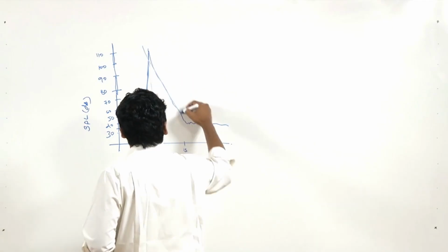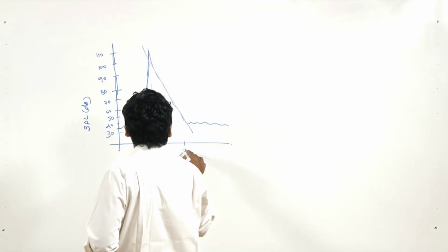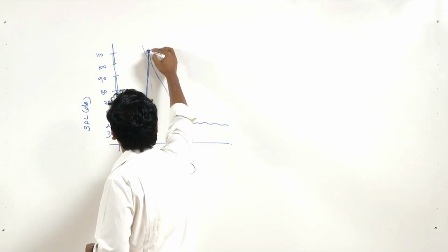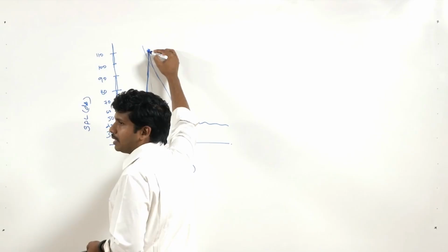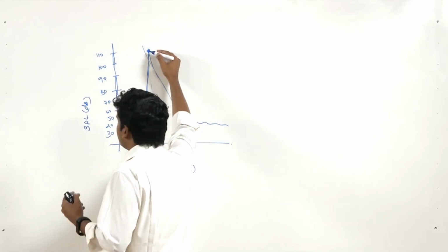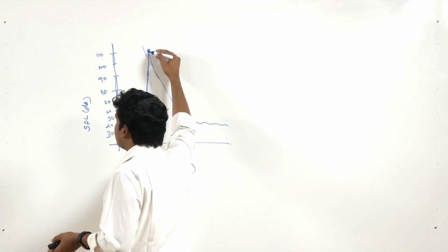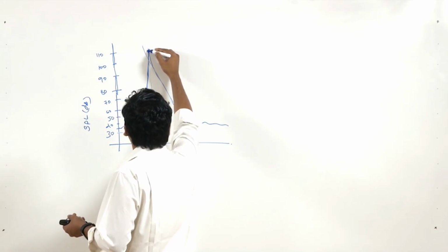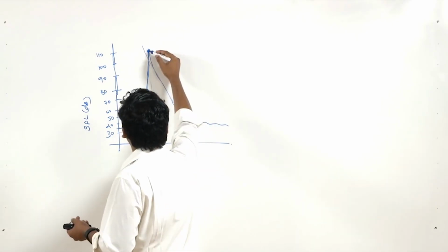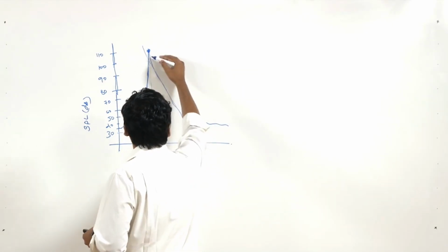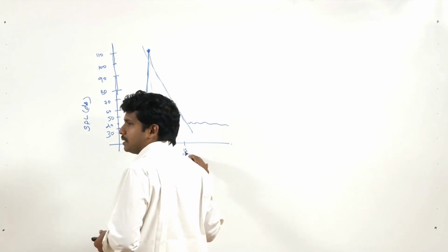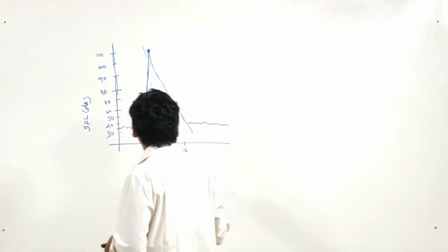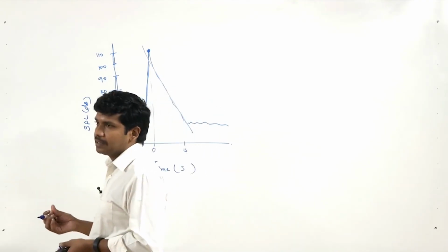The slope of this line is estimated, and the time taken between this and this is that of the reflections of the direct sound. So this is a direct sound at this point, this is a peak direct sound, it can be a clap, a gunshot, or a cracker or any standard sound source. You are elevating the background noise level and then you are letting it fall. The cracker is just one impulse, it falls off and takes about 1 second. This is exactly what you call reverberation time. It is expressed in seconds.